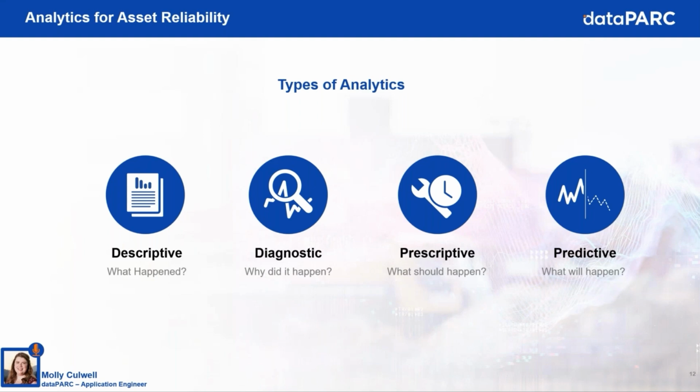Then we have diagnostic analytics, really understanding why it happened. This helps us uncover the root cause of the issue, allowing us to address them more effectively. Sometimes this is called exploratory analytics and also uses historical data to find the root cause of equipment failures with the aid of downtime tracking software. So sites can assign reasons and comments to collect the necessary data needed to analyze events afterwards in Pareto charts, and then go after those events that are causing the reliability issues.